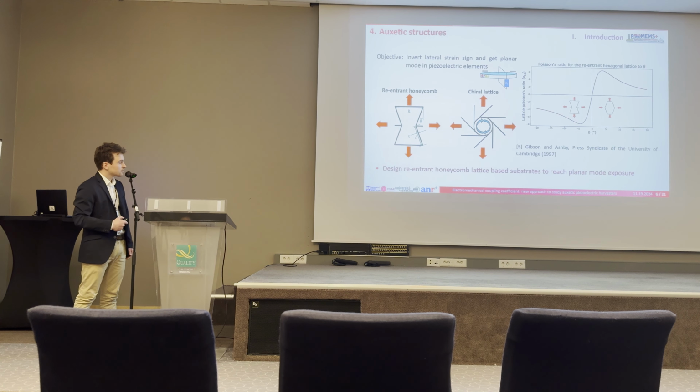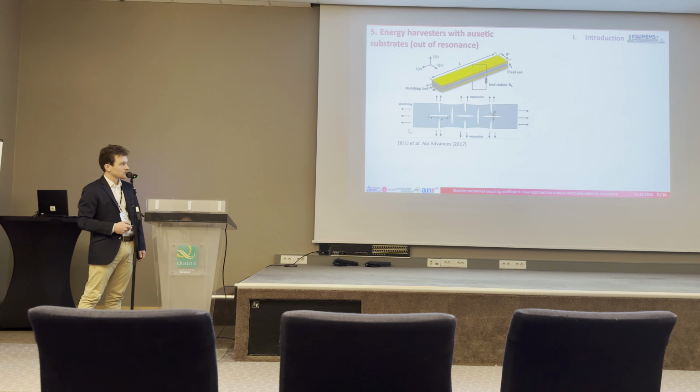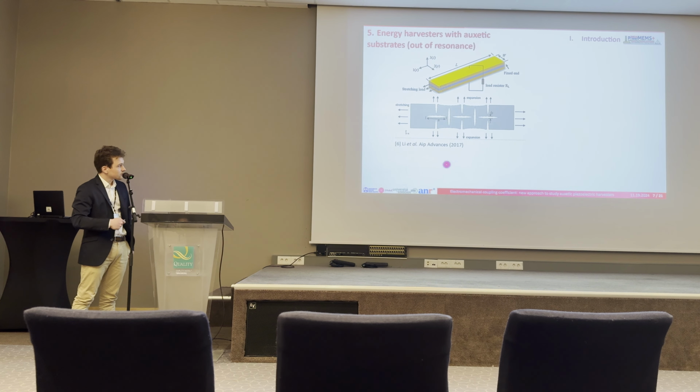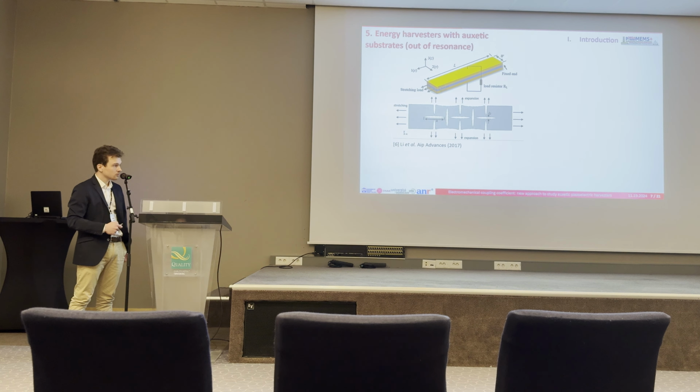So here we have some auxetic structures, and there are 2 cases to use this on piezoelectric harvesters. The first case is the energy harvester with auxetic substrates out of resonance. Here we have a work done by Lee et al. in 2017. They used an auxetic substrate made of steel with polymer material.